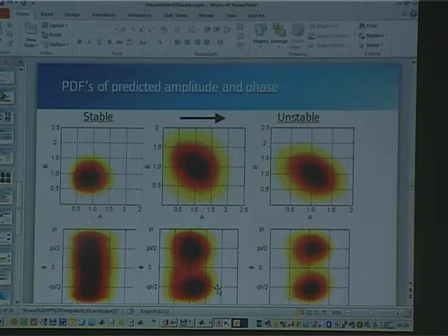But basically, uniform distribution between A and B means that the sinusoidal part and the cosine part of the mode are independent, randomly, stochastically fluctuating. If you go more unstable, they concentrate more around plus and minus pi over 2. It means that they get more of a rotating mode character, and if you continue that, it becomes more and more, and you could imagine that at the very end you just get dots there, and it's really a very unstable limit cycle oscillation.